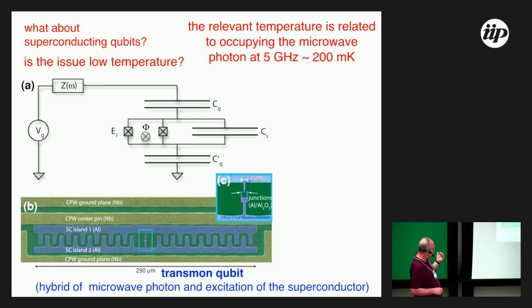And that nonlinearity is given to you by the superconducting system. The superconducting electronic device is this really tiny thing. Here's my L, my wire, and you can see a little blow-up over here. There are the two Josephson junctions that are giving you that nonlinearity that is essential for quantum computing, to detune the 1 to 2 transition from the 0 to 1. As I mentioned also on Monday, this is a very large object. This is 300 microns,